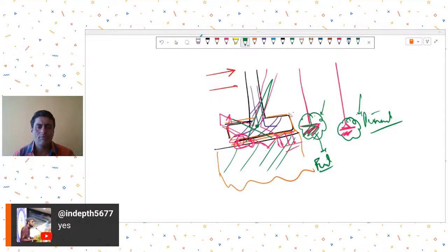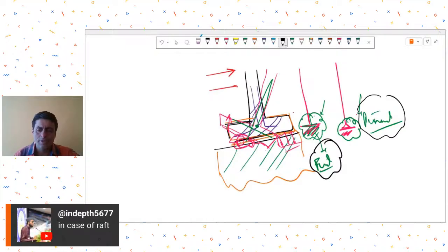So then, most of the engineers tell you that you may design your columns for both fixed and pinned, and then provide whatever is the worst case. This is also a practice that many people adopt, that they will analyze and design their columns, beams, etc., once assuming a fixed condition, once assuming a pinned condition, and then provide whatever is the worst.